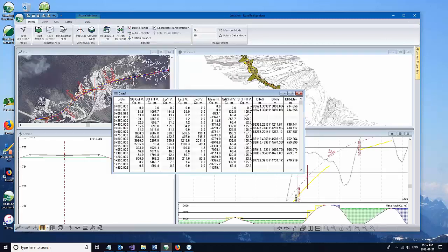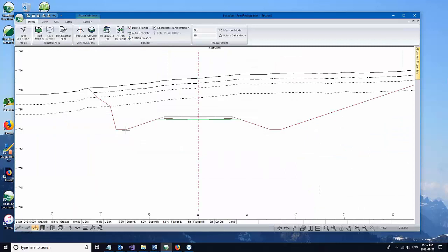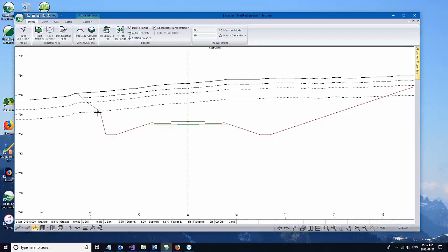So again, templates have point codes. How do you find out the point codes? You just poke around. You can move over what you think is an important point for you. DIL, DIR, road edge. These probably won't have point codes, but there are other ways to get that intersection point. Similarly, the surfacing points, you can pick those up for staking, whatever.